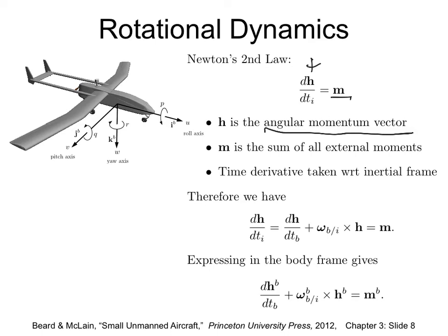So a similar approach, we are again differentiating a vector here, and it will be written the same. You have a linear part and a part because of the rotation, equal to the sum of all the acceleration moments. Later on, you will see that when the propeller is rotating, it gives a counter moment, so your aircraft kind of turns towards that, and we will have to take that into account as well.